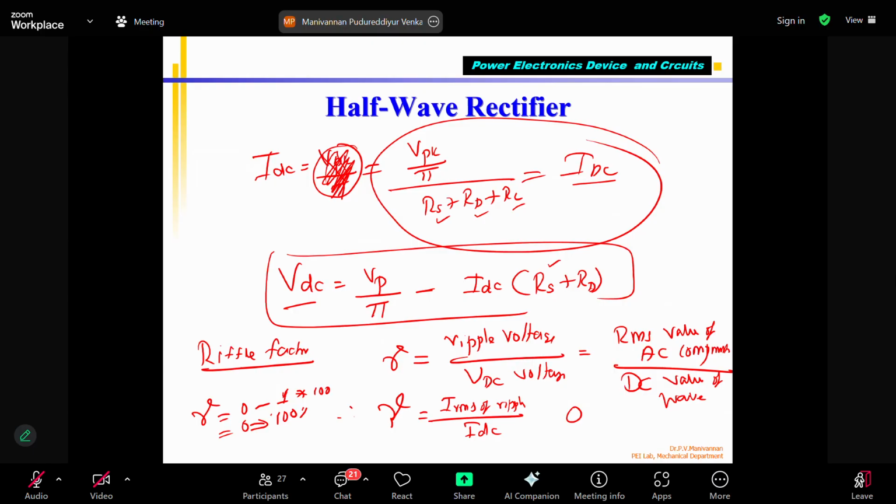Understood. That's how it works as a transformer. Just like the primary supply, the secondary voltage indicates rotor induced voltage. Once voltage is induced, the coil is already short circuited, so current flows. When current flows, it produces magnetic flux, called rotor magnetic flux. That flux gets locked with the rotating magnetic field and rotates along with it, so the rotor rotates. Since it is an induced motor, we call it induction motor.